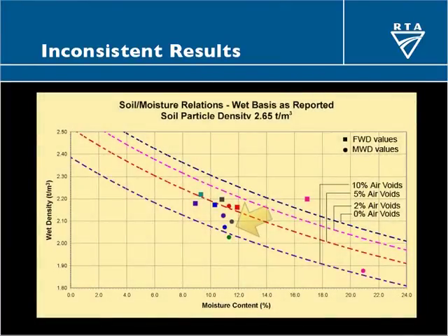Here we can see the laboratory results all show about the same optimum, but there's a huge scatter in the maximum densities. The field results perhaps look reasonable, although there is a bit of a scatter, but there's at least one set which is obviously a quite different material because the values are far over to the right, and the field result associated with it is just plain impossible.